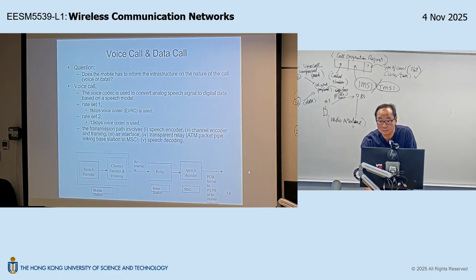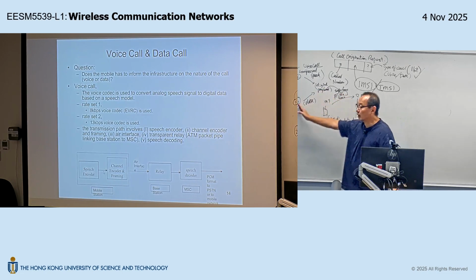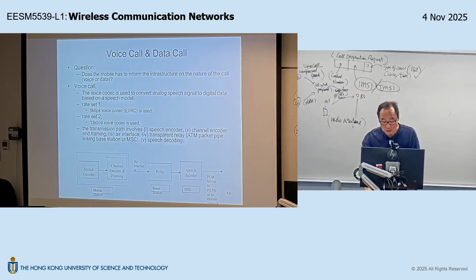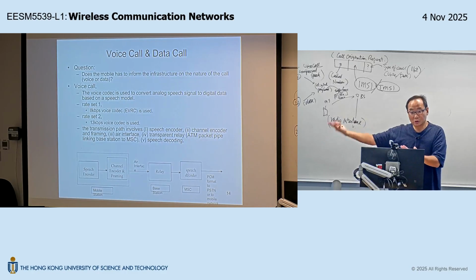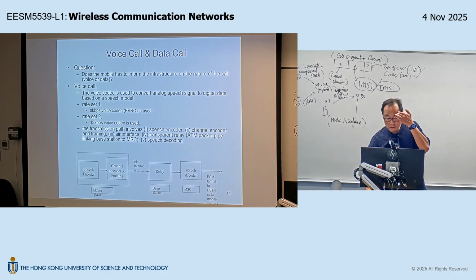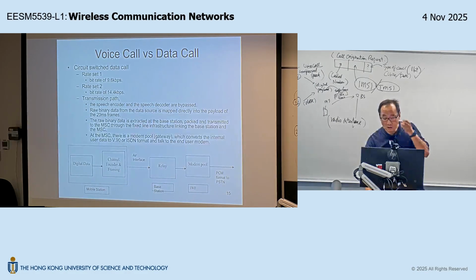Is that okay? Now, on the other hand, if you're making a data call, that means there is no speech encoder here. The digital packets are coming from a file. If that's the case, then it doesn't make sense for you to terminate this call with a speech decoder, because it's like feeding data to an MP3 decoder, but the input is not MP3 format. Then the output of the MP3 decoder will be rubbish, right? So if you're making a data call, then you need to find something else to terminate your data call.